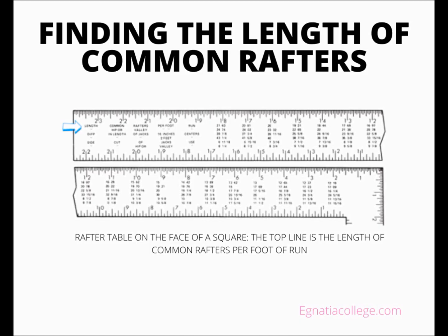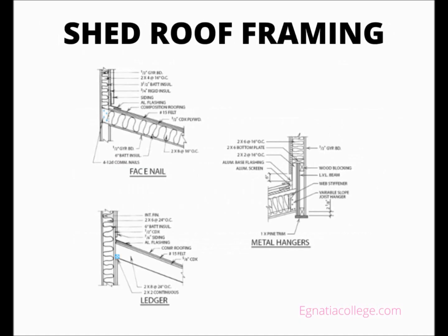Shed roof framing. Most of the lake house has shed roof construction. That is, the common rafters cover the full span of the area they cover in a single slope. To find the length of shed rafters, treat the entire span of the rafters as run. For example, the total width of the garage is 13 feet 9 inches. There is no overhang on either side of the garage, so the span of the garage rafters is 13 feet 9 inches.